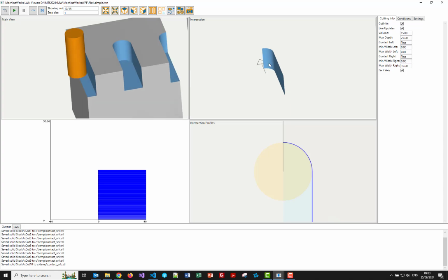I mean, as with anything, there's a trade-off between accuracy and performance. But the nice thing about the MachineWorks polygonal model is you can set the tolerance you're working with on a per tool basis, and you know that MachineWorks sweep volumes are going to stay within that tolerance. So you know the results you're going to get are within tolerance. With a sample data model, you don't know that. I mean, at the points where you have sample points, you might have extremely accurate data, but in between those points, you know nothing. And that's a pretty important issue when you're dealing with these kinds of problems.